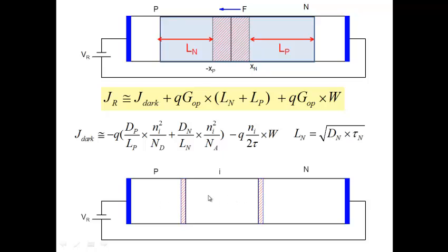And therefore you get better response time. So most of your photodiodes, for applications where speed is important, are not PN junctions. They are P, I, and N, deliberately enlarging the region where you have a high electric field. Otherwise, the electric field is high only in a smaller region here. And you enlarge it by making it completely I.